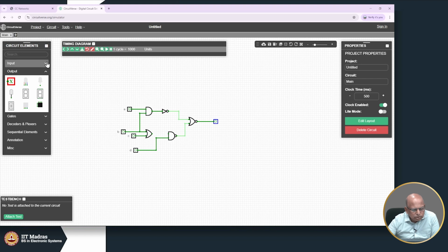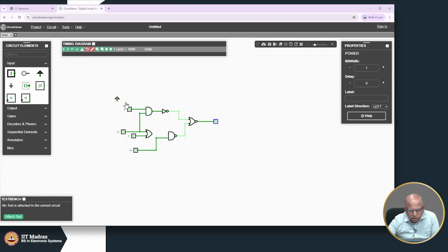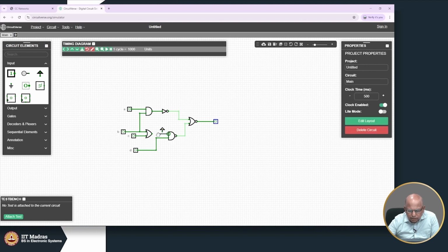Okay. So a stuck at 1 fault can be simulated by putting a logic 1 here and connecting it there. Okay. So when I put a 1 here, see, unfortunately this 0 is already producing a 1 here, right, and as a result you will get a 0 here.